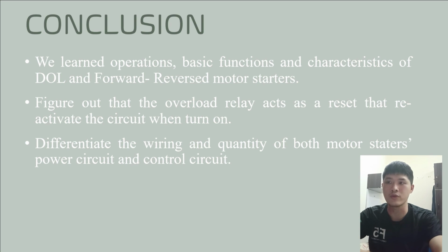As a conclusion, we learned the operations, basic functions, and characteristics of DOL and forward reverse motor starters while doing this lab sheet. We also figured out that the overload relays act to reset and reactivate the circuit when turned on. We also know how to differentiate the wiring and quantity of both motor starters in the power circuit and the control circuit.